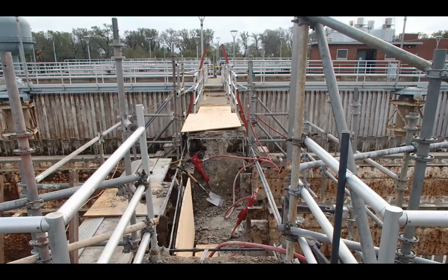This is one of the walkways. This is the amount of deterioration that's occurred, that the entire walkway had to be removed. As you imagine, if you're in a water treatment business, you use chemicals in order to treat the water. Those chemicals aren't necessarily very favorable to reinforcing steel and concrete. And so there have to be protective coatings and durability measures in place. Sometimes it still gets out of hand. And so in this particular case, the entire walkway had to be removed and replaced because of the amount of deterioration. So that would have been picked up on the inspection process.